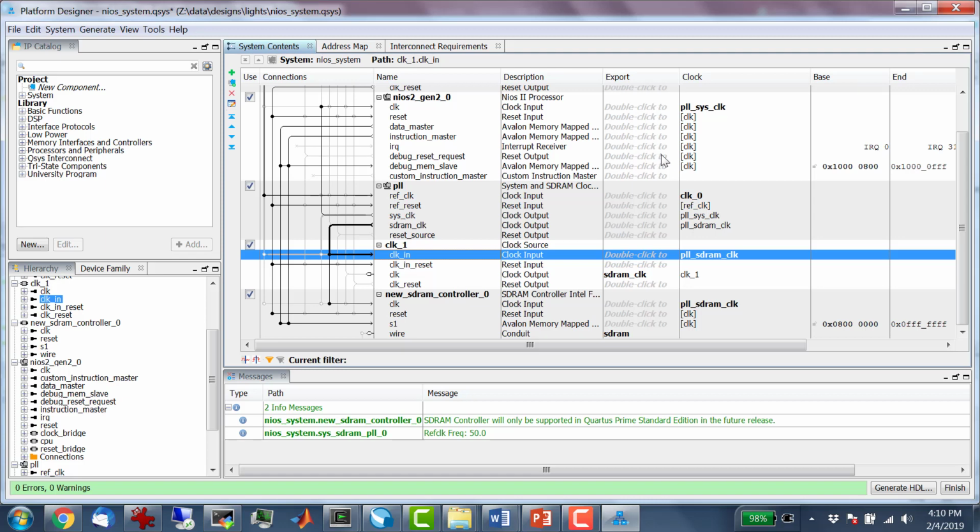Sorry, does it get carried over the USB Blaster, which is USB, right? So we have this one cable where we can program the FPGA and get the console. You guys with me? Make sense? So we can print messages. We can also type stuff in as well, although generally we don't do that in this class, but you have the option of doing that.